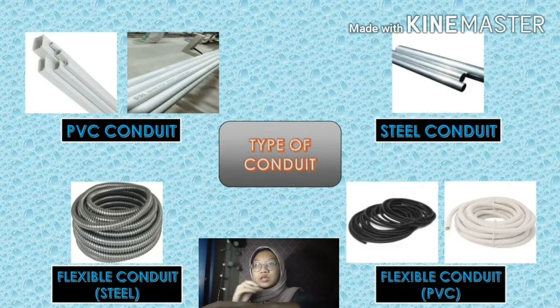For flexible metal conduit, it is typically available in diameters between 3/8 inch and 3 inches, but larger sizes can sometimes be found. It is made by coiling self-interlocked aluminium or steel strip, which forms a hollow tube that wires can be pulled through. FMC comes in standard wall, sometimes called full wall thickness, or a reduced wall thickness. Most manufacturers also produce an extra flexible FMC for tighter bends, but this is generally not UL approved.